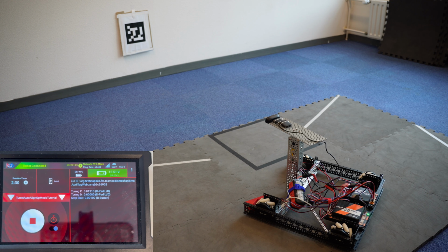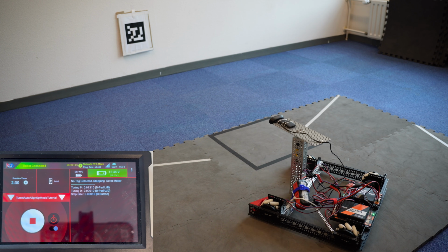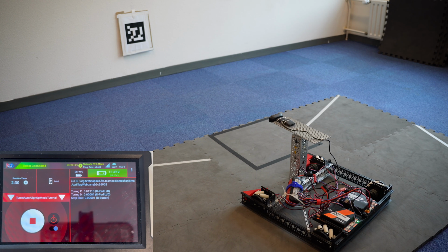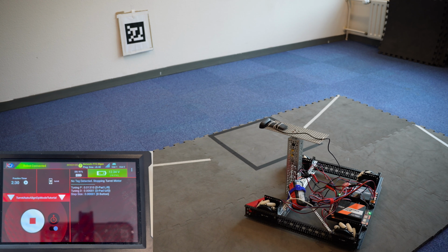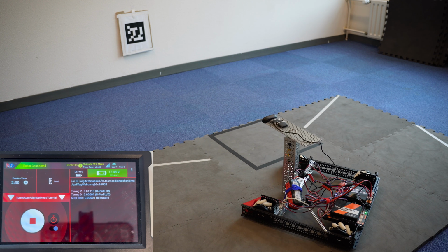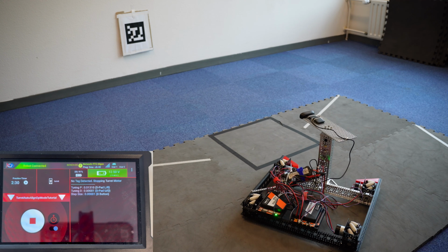All right, so now let's actually start doing our D value. I'm going to bring my step size down, and we're going to increase our D value to 0.0001. We're going to look to see what that damping is. We see we're actually sparking left and right, so I'm going to do 0.001, because I find that these systems are very sensitive to D value changes. We can see we're still overcorrecting a bit too much on that. So let's move just a bit. It looks like our D value is still probably a little bit high.